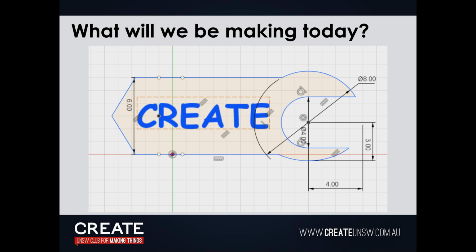Next thing we'll do is we'll select this entire thing. If you do that, you'll notice that here it says sketch 10. It's highlighted down here. Now for laser cutting, we'll just right click on that. Oh, sorry. You actually have to stop the sketch for that. So yep, stop the sketch. Right click. Here we go. Yep, save as DXF. Hit save as DXF. I'm just going to check on the desktop right now. Create spanner. Right, that's done.